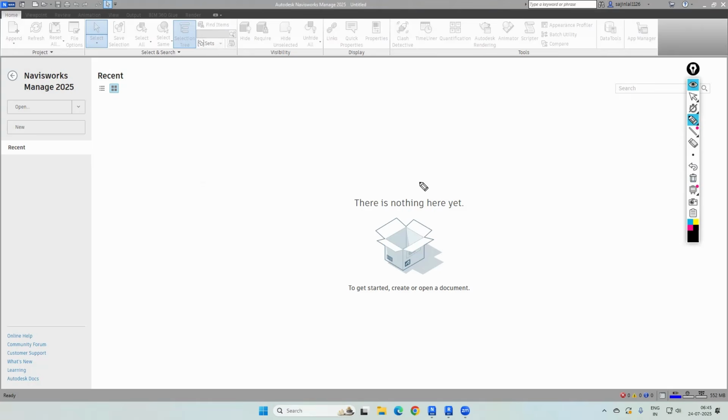See, Navisworks, very important, the next session, Navisworks file sets or file types we are having. See, normally we are having like 3 types of Navisworks file types: NWC file, NWF file, and NWD file. Okay. So means NWC Navisworks cache file, NWF Navisworks file set, NWD Navisworks document file. So what are the differences of all these files and what all functions that we are having for NWC, NWF, NWD that we can use?